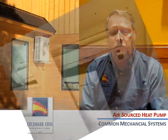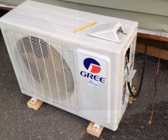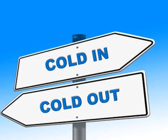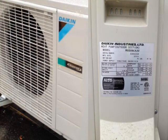So an air source heat pump is a system that can actually transfer heat from the outside to inside the house. This happens when the refrigerant is circulated between the two coils, one indoors and the second outdoors. So it looks just like a regular AC, except it has the ability to reverse the refrigerant flow. The indoor coils release the heat as the refrigerant condenses back into liquid form. This process can be reversed for cooling.